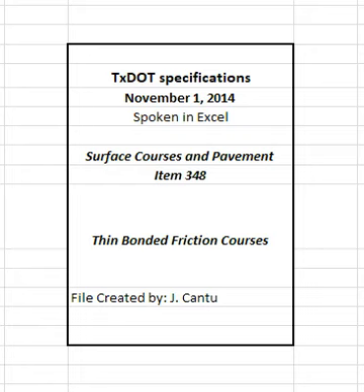The engineer will perform testing before the start of production and may perform additional testing at any time during production. The engineer may obtain the coarse aggregate samples from each coarse aggregate source or may require the contractor to obtain the samples. The engineer may waive all Micro-Deval testing based on a satisfactory test history of the same aggregate source.